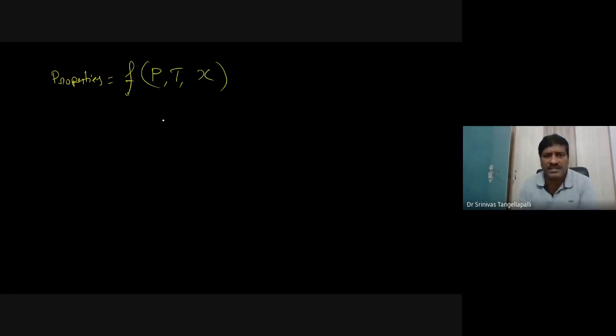During phase change in a single fluid system, either pressure or temperature is enough, because there is a relation between the saturation pressure and saturation temperature. That's why there is no need to supply both the saturation pressure and saturation temperature in the single fluid system. In a binary fluid system, the concentration is mandatory even though phase change takes place, because just now we saw that during the mixer, the concentration is changing for the separated liquid and also the separated vapor.